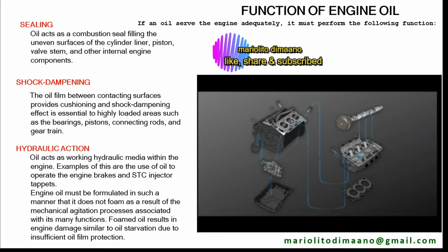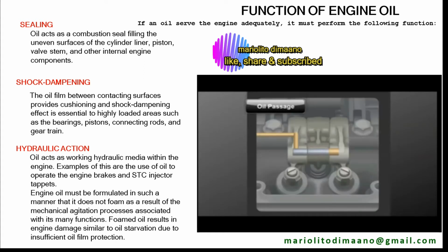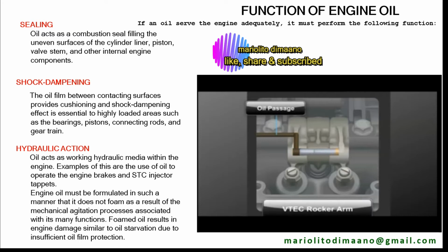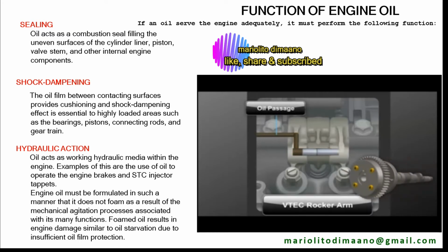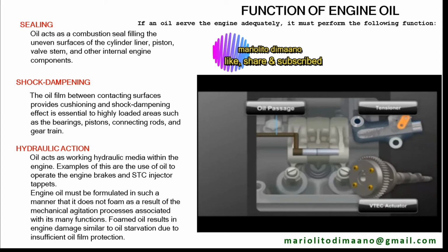As oil flows through the engine, it also removes heat from friction points isolated from the cooling system. Finally, vehicles use oil as a hydraulic fluid, engaging components such as VTEC rocker arms, VTC actuators, and the cam chain tensioner.